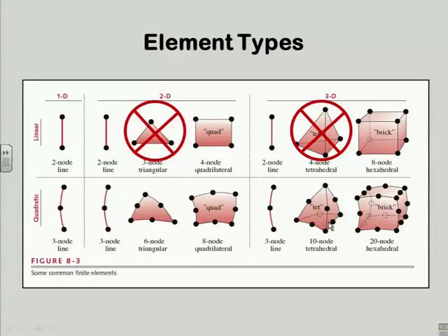However, if you move up to the quadratic, then the tet is fine, and then triangular is fine, because now I can see the variation along the edges sufficiently well. So it's only these linear versions that are considered to be too crude.